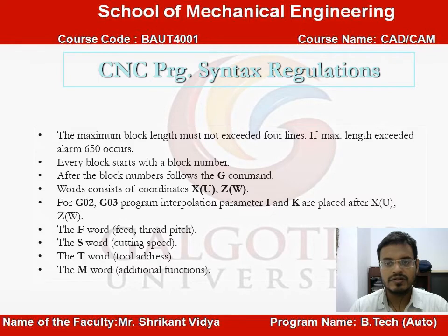There are syntax regulations for a CNC program. The maximum block length must not exceed 4 lines. If the maximum length is exceeded, an alarm occurs. Every block starts with a block number. After the block number follows the G command. Then it consists of coordinates X, or in other controllers U or W.